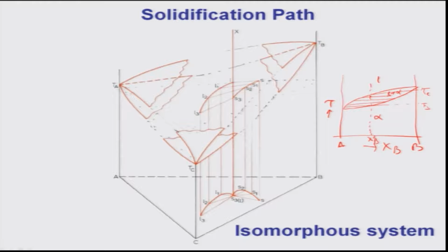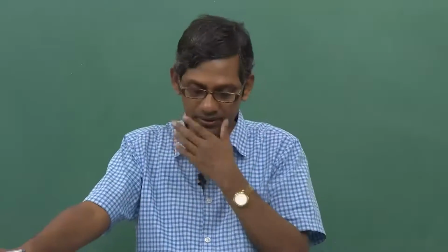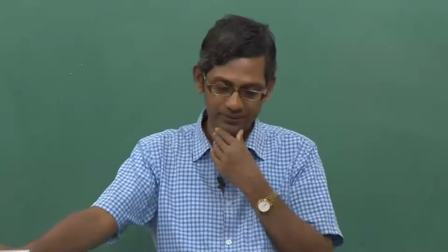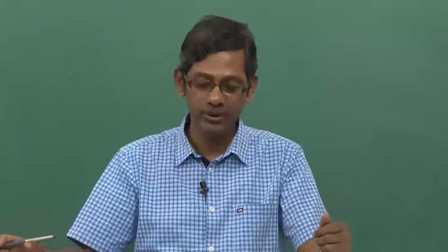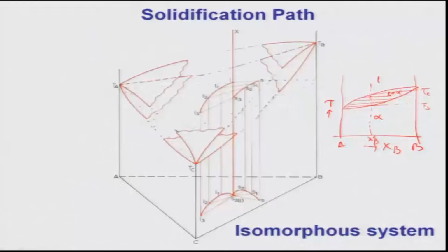That is what happens. And you know that if I cool it very slowly, in an equilibrium manner, then the solid will have a uniform composition. But when I change the cooling rate or go for a non-equilibrium manner, then it will lead to coring, that I have discussed. Now, let us do that for ternary sections. To show you clearly, what I have done is that I have cut the middle part out. As you see here, these are my solidus and liquidus surfaces. Okay, you can clearly see this is the liquidus, the top one, and the bottom one is the solidus surface.